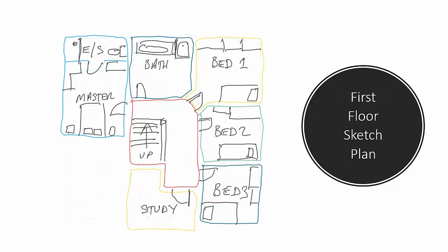Looking at the upstairs then, we have a bit more space and a bit more detail in relation to these bedrooms. It is quite tight to fit all these in, and sometimes there's little tricks and tips can be used, maybe putting one of the doors at a 45-degree angle just to get into the bedroom. That will affect the likes of bedroom 2 there and the bathroom, and that makes it a bit more complicated if you're trying to fit furniture into certain areas, so please be wary of that.